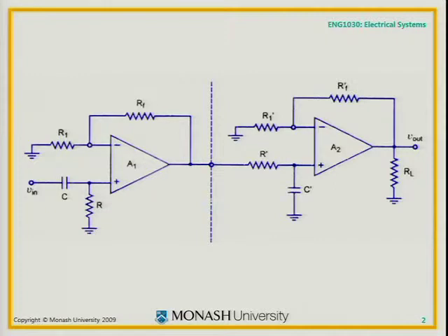With just resistors, I can't get that. The behaviour is just V equals I times R. It doesn't matter what the input looks like. But with capacitors and inductors, it does. There's a frequency-dependent behaviour. It allows us to do things like build filters.